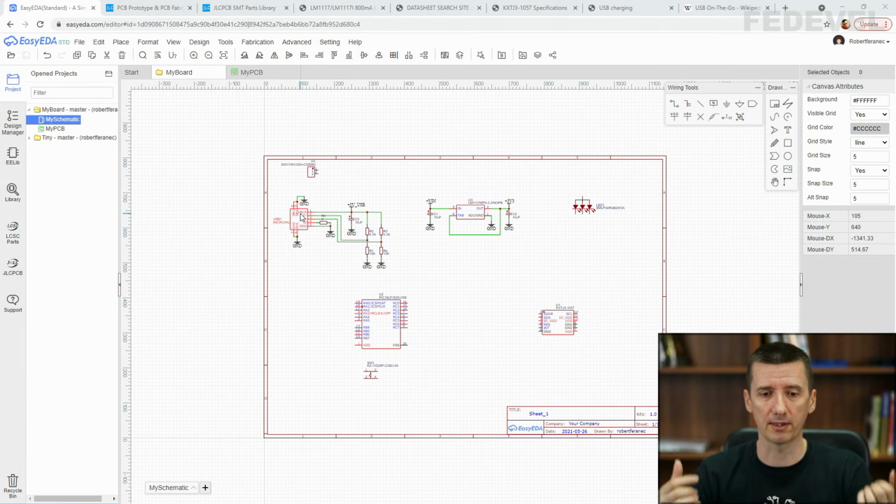together. For example, if the voltage on the battery is higher than 5 volts, then this power from the battery would like to go inside of this power supply on the USB. And also on the other side, if the voltage on the battery is lower than the 5 volts coming from the USB, then this 5 volts from the USB would try to go inside of the battery. And a very simple way how we can prevent this fighting is to use diodes.